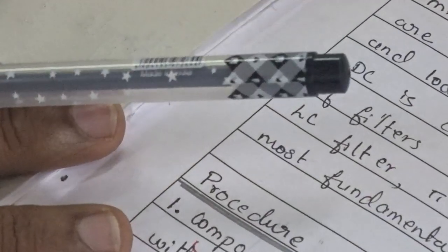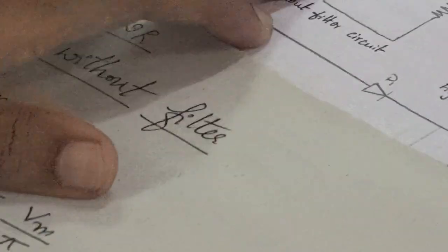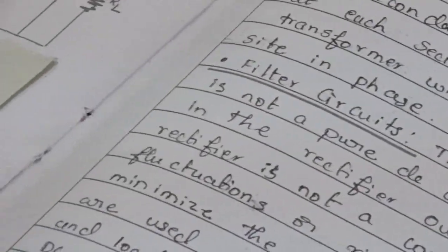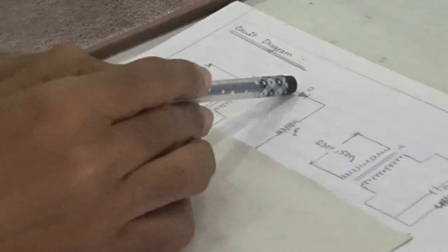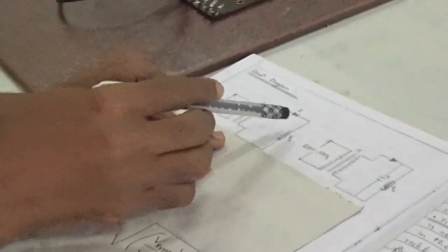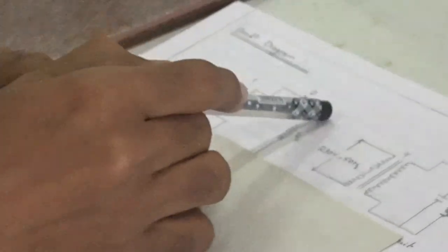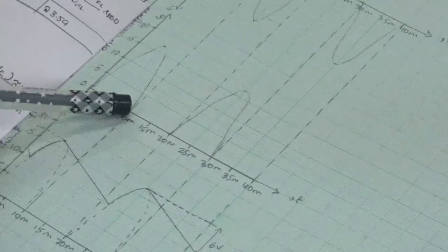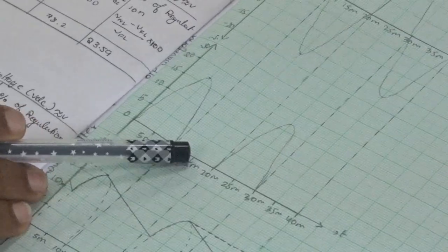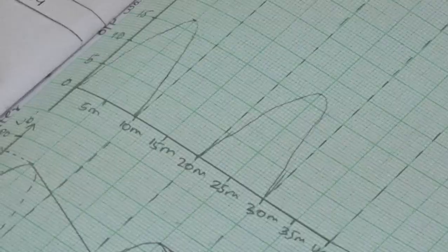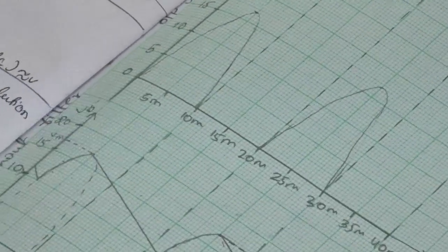During the negative half cycle of the input, the diode will act as an open switch, which means there is no connection between the input side and the output side. So the current will not flow through the load resistor, and the output will be zero. Hence for the negative half cycle of the input we get a zero output. This means that the half-wave rectifier uses only one cycle of the input, not the complete cycle of the input.